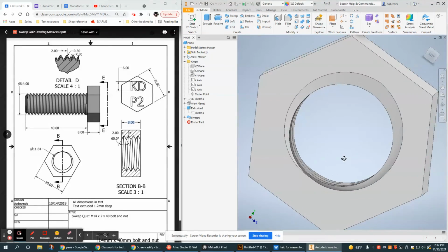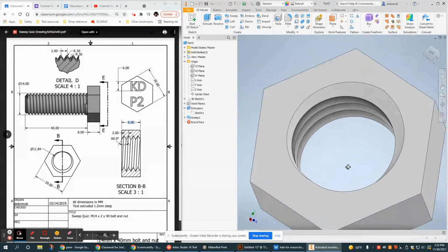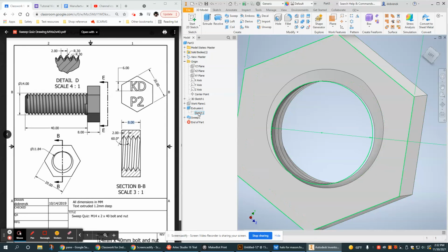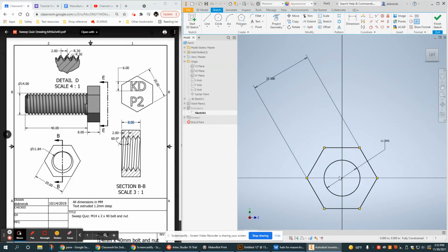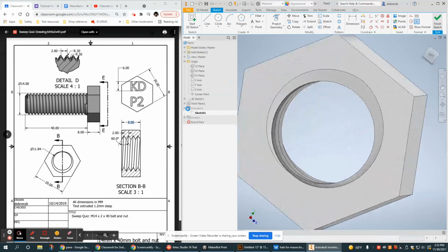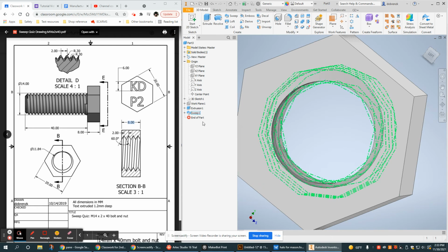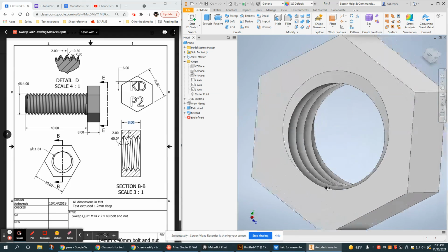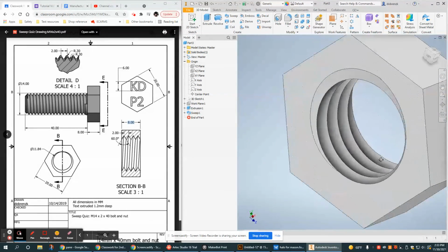One thing to keep in mind is depending on the tolerance of your 3D printer, which we're going to be 3D printing this in class, if you have too much interference, what you can do is open the tolerance up a little bit by making the hole here a little bit wider, or you can go to the 3D helix design and make that slightly larger to add in a little bit of tolerance for these 3D printers that, 20, 30 thousandths is pretty normal for an off the shelf type of 3D printer. Something very, very expensive can be more accurate, but that's not what we have access to, especially when we're just starting out. So that's the nut.